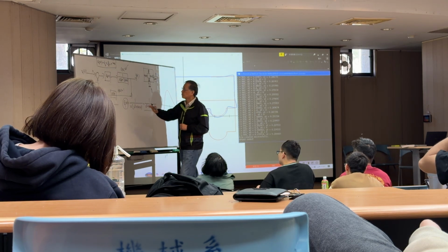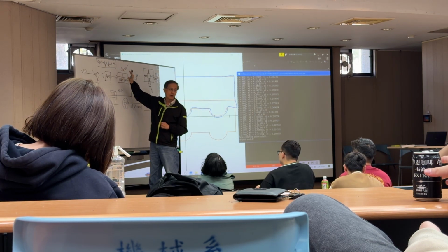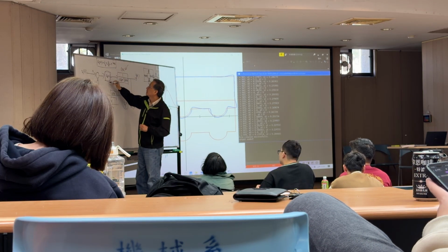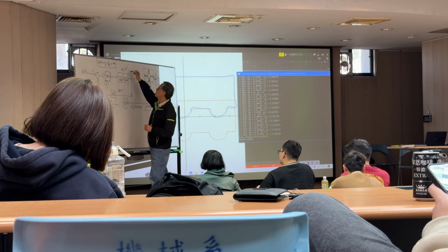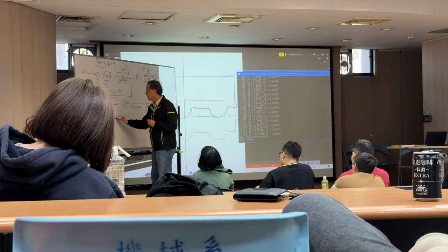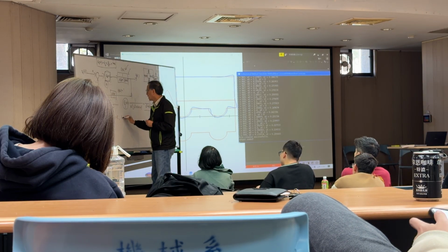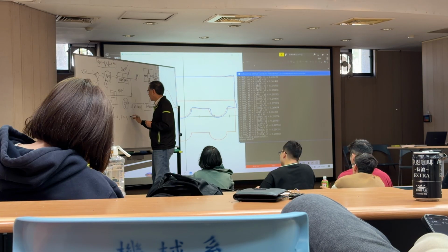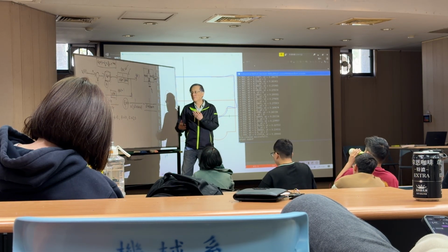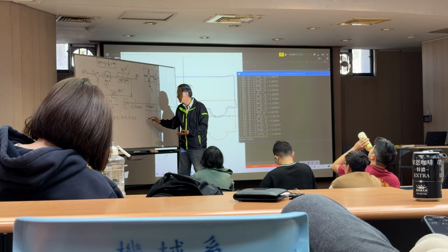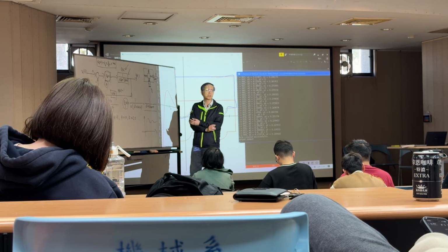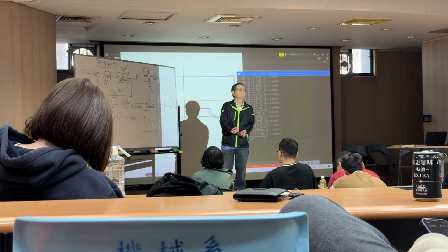So the first problem, A, is to repeat what I showed you today. And you can change the K value here, and this is your G(s). Then try K equals 5, K equals 10, and K equals 20, just like I did today, and run the step response, just like I showed you today.